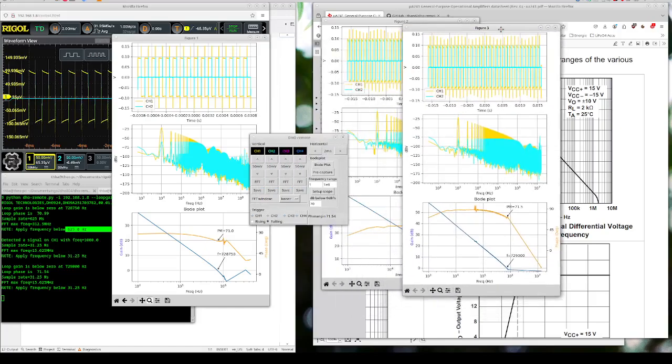There you are. So now it does cross, but there is also a straight line here, and that's because there is also a point picked up at 20 megahertz. We're not interested in 20 megahertz. So what I prefer to do is just limit the output to 2 megahertz and do a capture again. I can also zoom in here, basically that would be the same, but well, I'll show you.